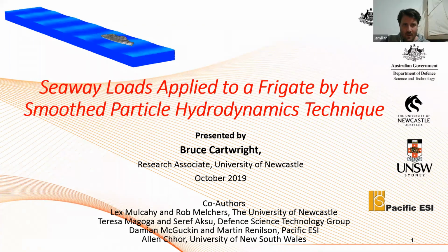From Andrew Baglin: have you looked at more complex wave states, such as JONSWAP spectrum type waves? Look, that's certainly on the cards, and that's our aim in the next phase of the project. But our aim to date has really just been to satisfy ourselves that the response is appropriate, and for that, a single frequency seems to work right. We've thought about it. It's not going to be easy through a moving floor, but it should be possible. I've certainly demonstrated more than one frequency at a time in the waves.